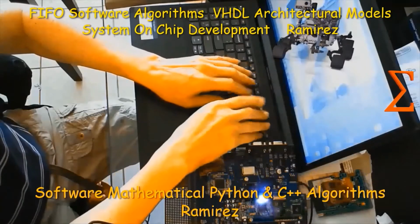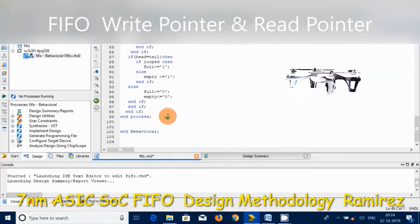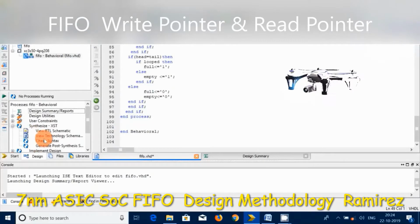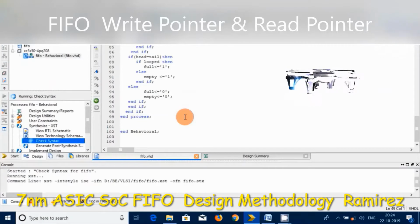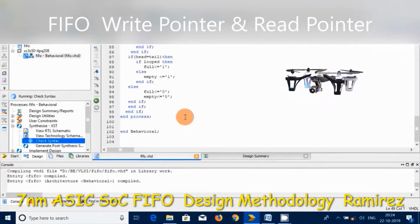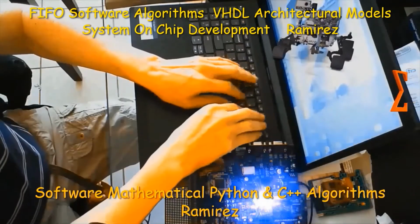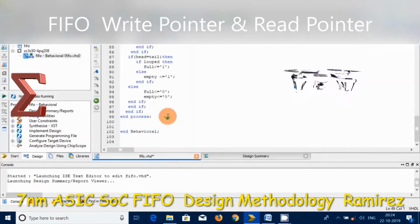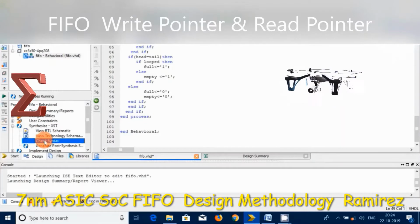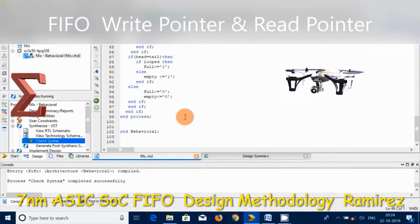The FIFO module has two settings that can be configured to adjust the width and the depth of the FIFO. That is, the DATA_WIDTH variable adjusts the size of the data in and the data out buses, so that you can write different sizes of bytes if needed into the FIFO. FIFO_DEPTH variable adjusts how big the internal memory of the FIFO is.